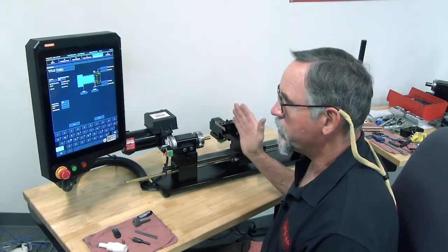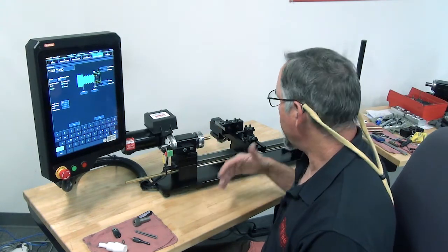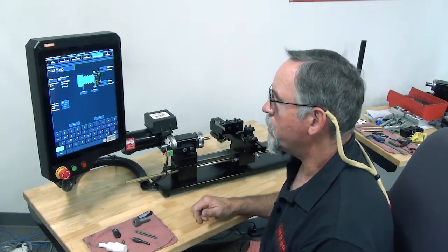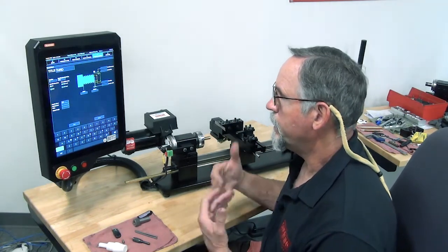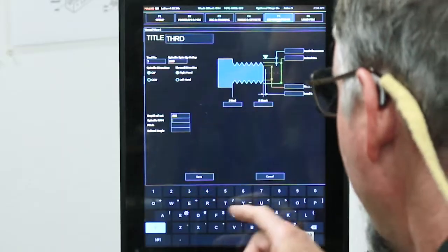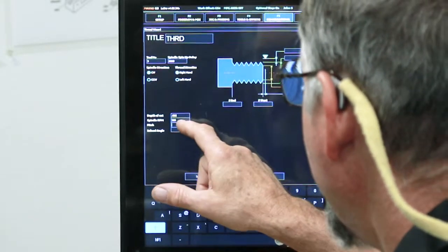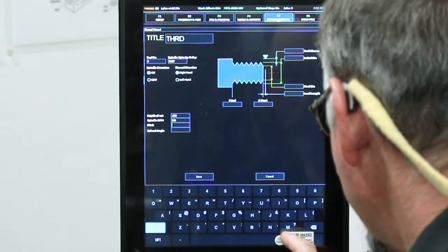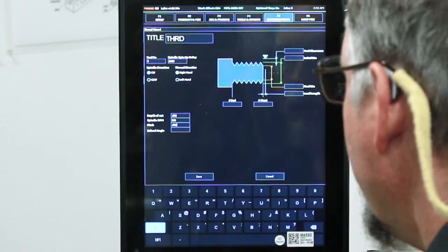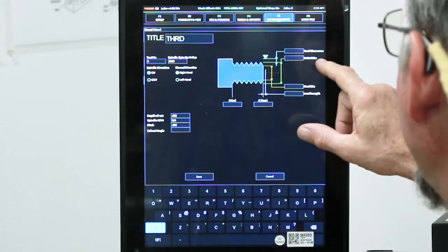it's a 32 pitch thread, I'm turning basically 30 thousandths per revolution. The capability at 70 inches a minute of the stepper motor is going to be exceeded if I'm turning that RPM and that feed rate. For the most part, you're looking at RPMs of about 300 thousandths, 300. The pitch on this is 0.032.